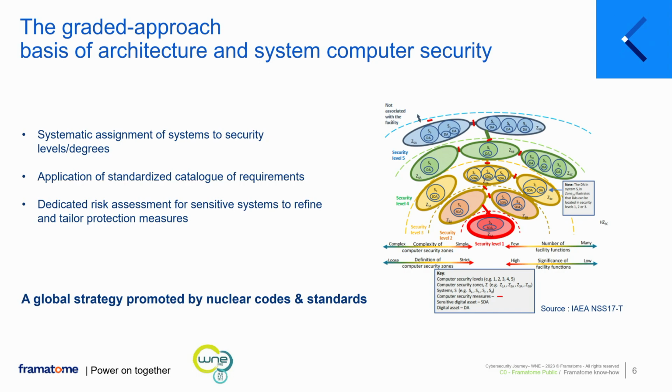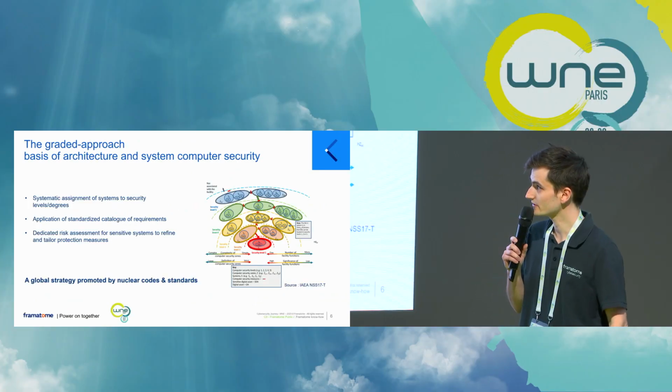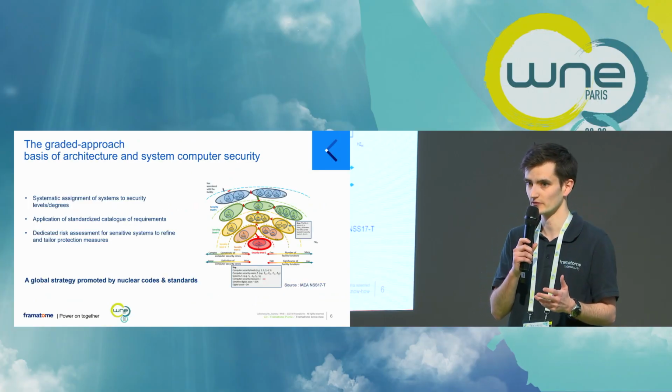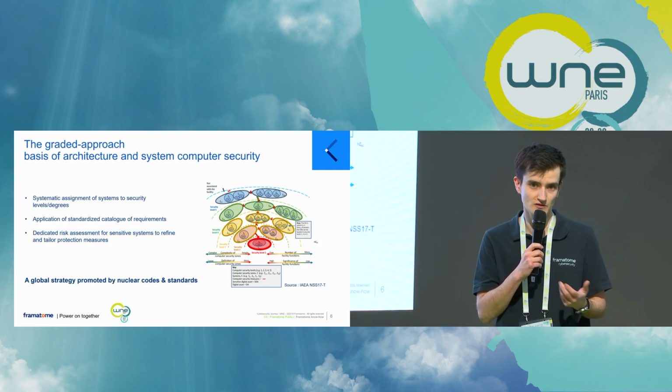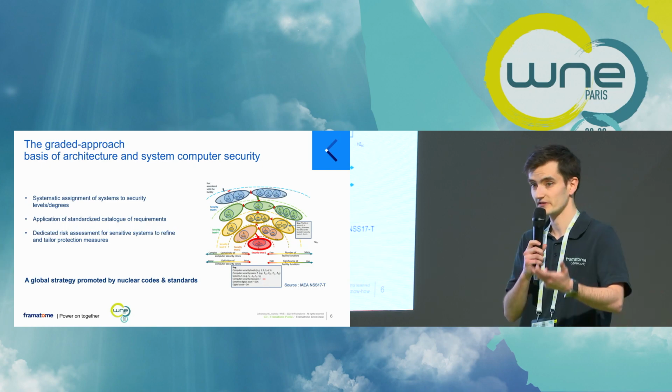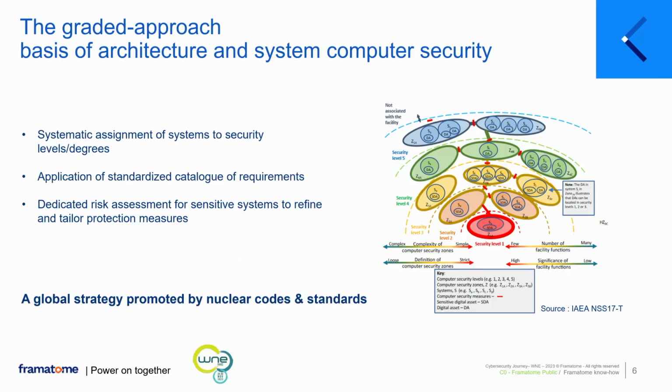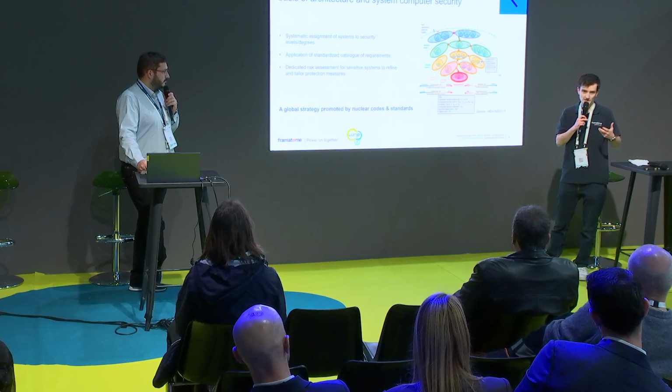Related to the technical part, the way to proceed is to have a systematic assignment of security degrees or security levels to systems depending on their criticality to the plant. Once it's done, we can implement technical measures on each of these systems related to their own level. Then this is reinforced by grouping and separation into security zones, to make things go together depending on their needs for communication, their needs for separation, and their consistency with security needs.